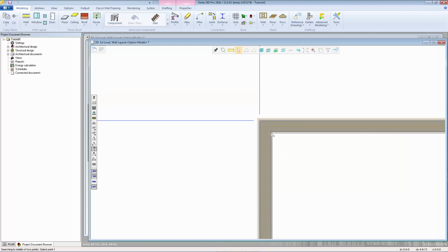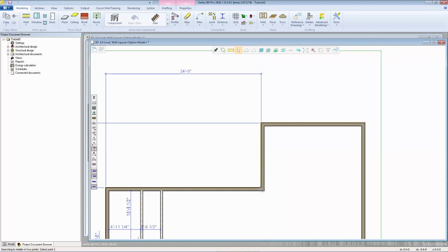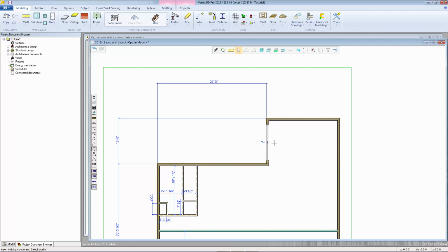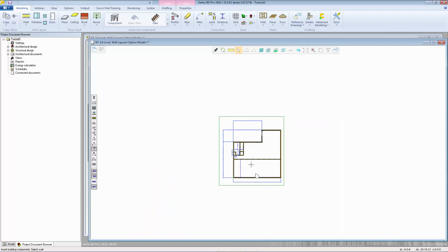So I'm going to select this interior framing corner for point 1. Now it's waiting for me to select point number 2, and that'll be this point here. As soon as I select that second point, it puts the middle of the door halfway between those 2 selected points. I'm going to hit confirm again, and now I can select another wall.